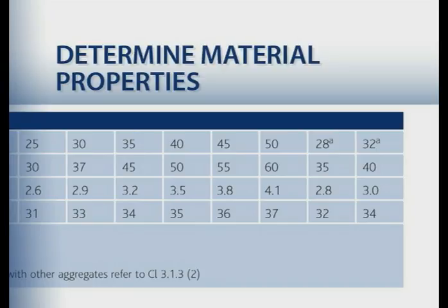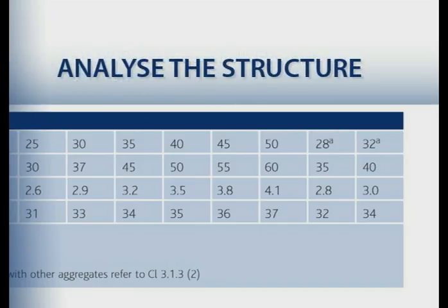And finally, analyse the structure, determining the distribution of internal forces and moments so that the critical design conditions can be identified. OK, Charles, that first step should be simple, determining the design life. They're all laid out in BS EN 1990.